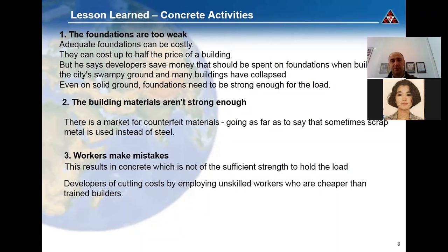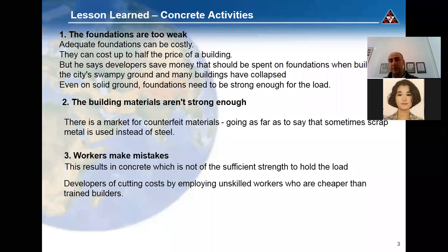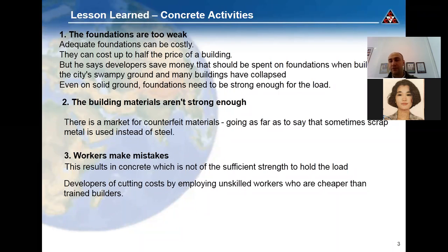That's very important. And not only concrete should be tested, but also steel. So steel, I mean the reinforcement, should be tested. You need to cut off the welded reinforcement from the main constructions, like columns, for example.